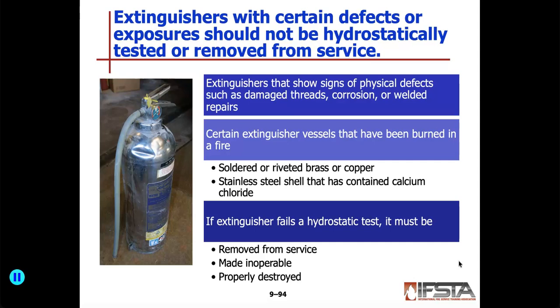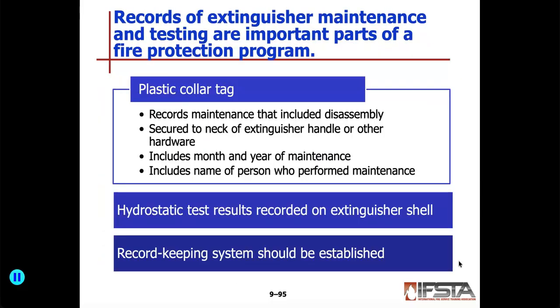And then if an extinguisher fails a hydrostatic test, it needs to be removed from service, made inoperable, and then sent to be destroyed. You don't want to try to fix that and put it back in service.